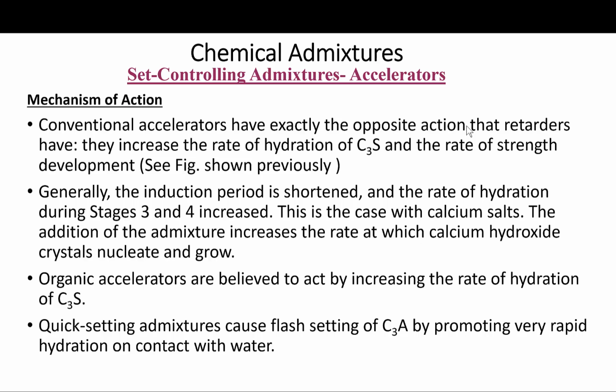The quick setting admixtures cause flash setting of C3A by promoting very rapid hydration on contact with water. So admixtures that affect C3A hydration can also be expected to affect the expansion characteristics of expansive cement. Remember this, when expansive cement is being used, any of these accelerating or retardant admixtures should be used with care and without full testing and basically understanding its effects. I will not use it.